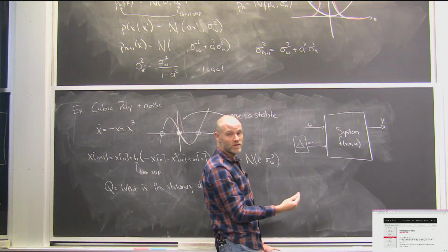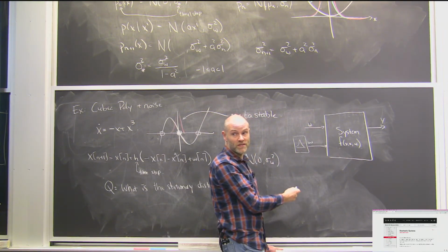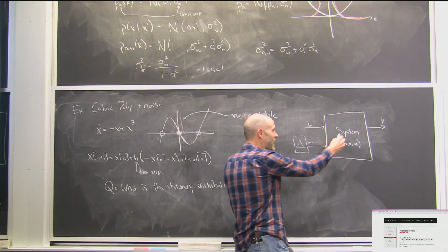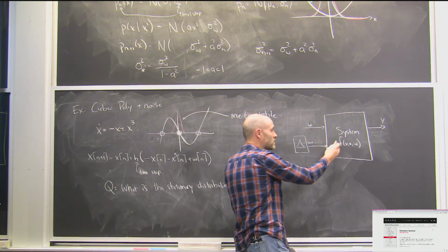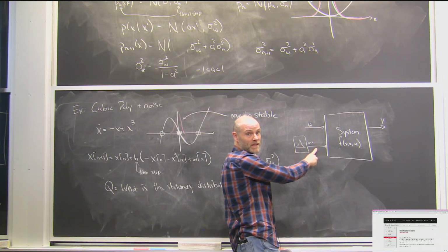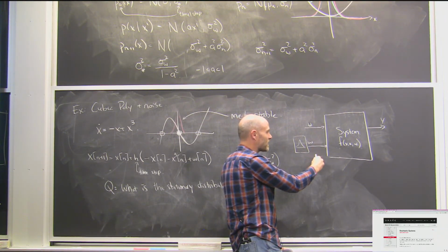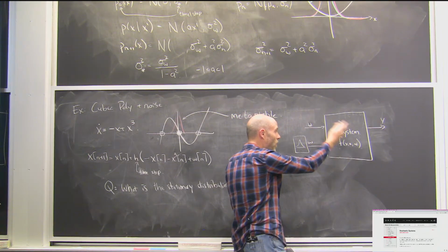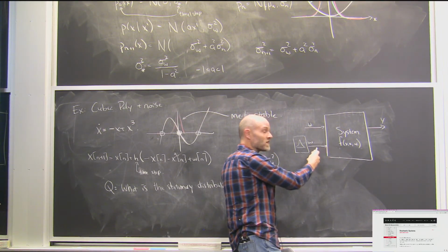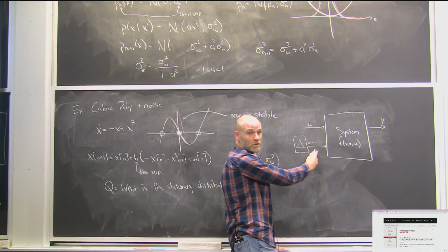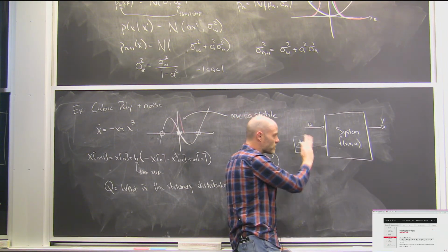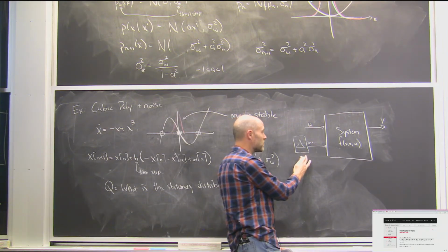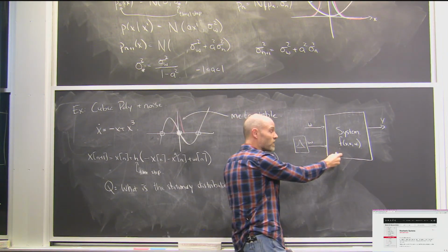Moreover, when we do the control design, this is the standard picture you'll see in robust and stochastic control. And the control design philosophy, I can ask any system or any diagram to, for instance, take gradients with respect to its randomness and get a sense for the covariance matrix, right? And I can write explicit verification, control design, system identification tools, all in this beautiful sort of framework, as long as I know which ports you're calling random, because I'll treat them a little bit differently. Okay, so there's plenty of tools for doing stuff with random processes in Drake, but there is a strong philosophy that please don't call rand in your generator.